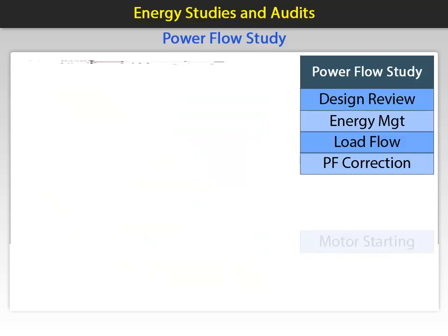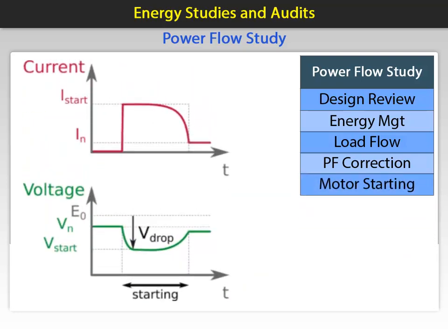Motor starting analysis helps prevent voltage dips, inrush current issues, and mechanical stress during motor operation. Large motors can impact system stability if not properly managed. Larger motors can also have an effect on demand charges on the utility bill. These are the items that the study should include.